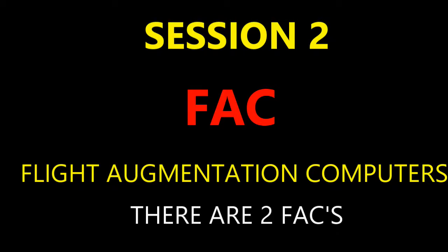All right, so let's talk a little bit about, I mentioned yaw damper and how the FAC is getting involved with these different things. Let's just suppose that we have a normal configuration. When you have the FAC push button pressed in, it's normal configuration. You're not going to have the fault and off lights on. They're going to be off. Okay. And so everything's good.